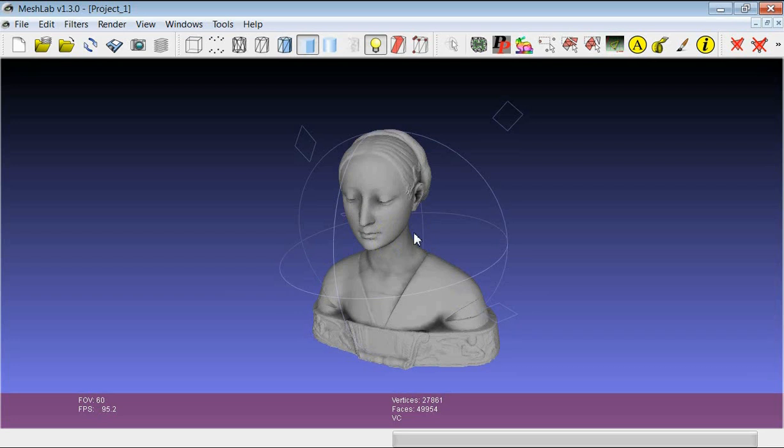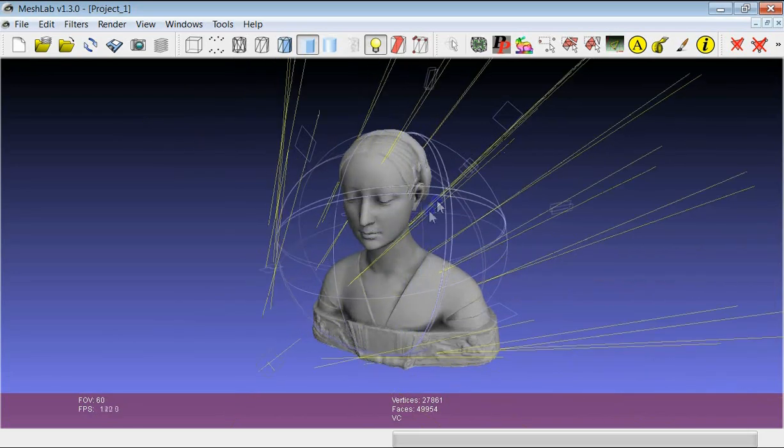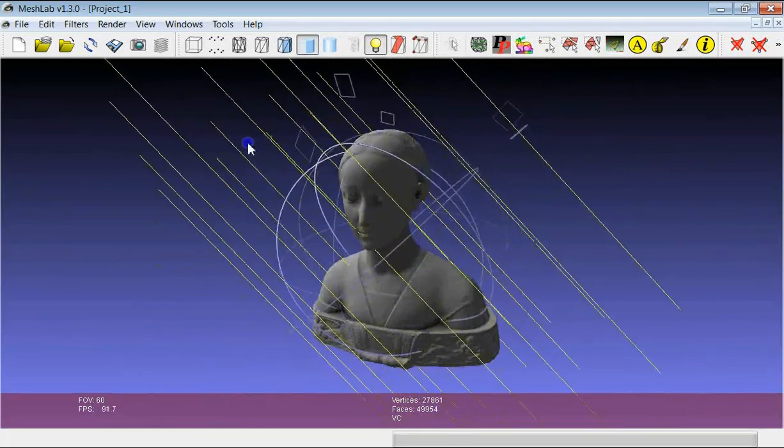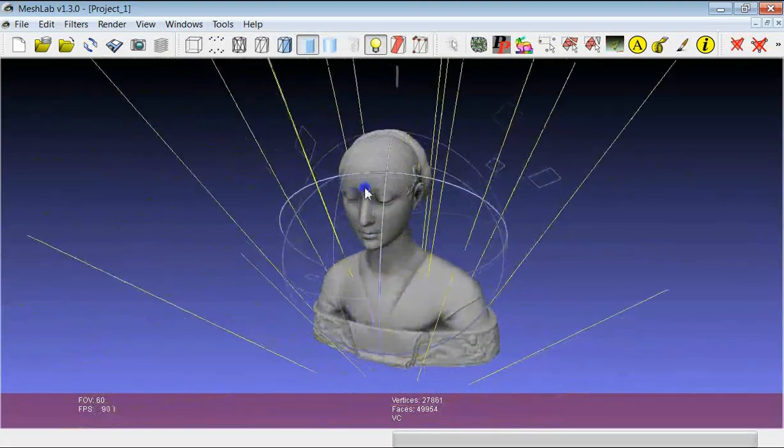of the light. The lighting in MeshLab is extremely simple because this is essentially a mesh processing tool, so there is no real way to set up a scene like setting several lights. But anyway, there are some ways to change the lighting that can be very useful, and the most basic one can be obtained by pressing Ctrl Shift and dragging, and you see here that you can change the direction of the light, which is illuminating the model.